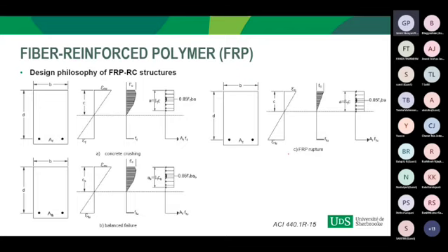In this case I have written FRP, but consider it as steel. In steel, we first yield the steel, which provides ductility to the structure. If we follow this approach, and as we know that fiber reinforced polymer is linearly elastic up to failure, what will happen? The structure will have fiber reinforced polymer rupture first. When it ruptures first, the structure will fail in a brittle manner. We never want our structure to fail in a brittle manner during earthquake loading, right? Therefore, to avoid this situation, the over reinforced section, where the concrete fails first, is chosen for fiber reinforced polymer concrete structures.